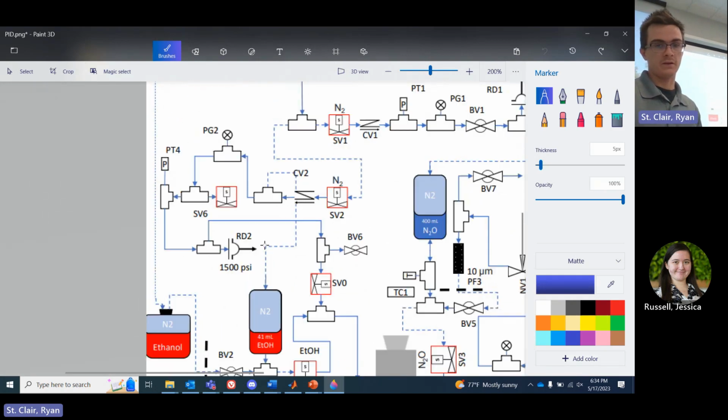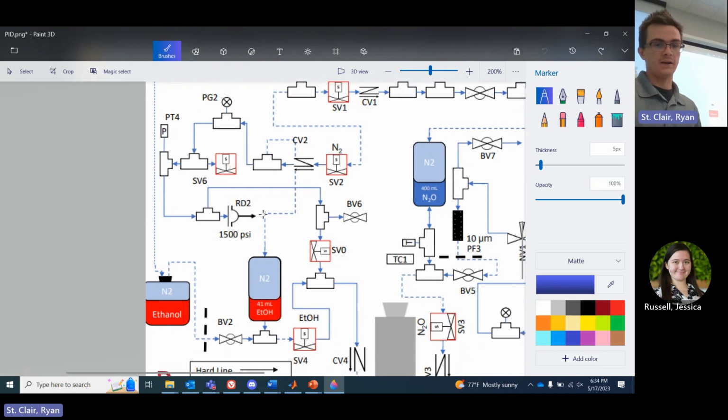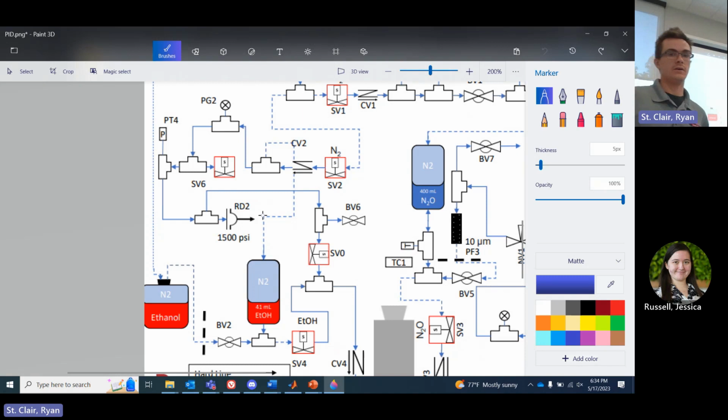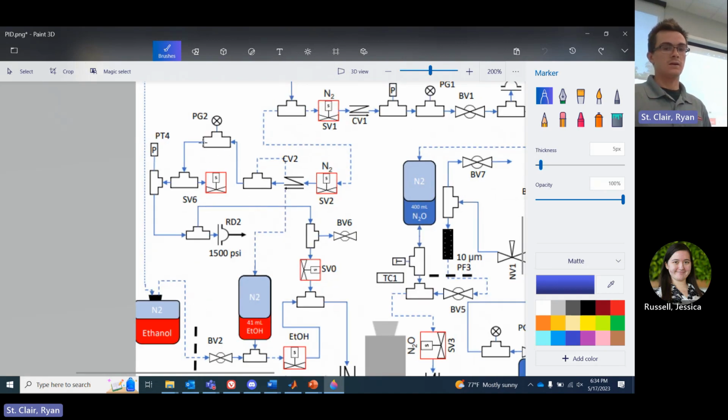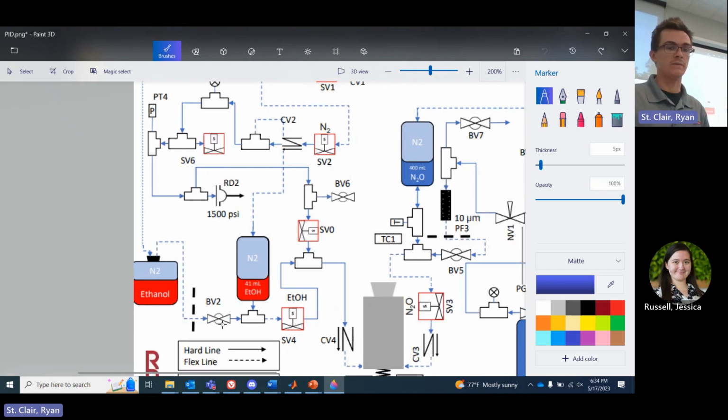And basically, I've just walked through all the components here. So it really is a step-by-step breakdown, looking at what different components do and why they're there. You can really start to understand that with a P&ID, and it also shows very well the relation of what lines are seeing the same pressure. If you're familiar with electrical engineering principles, if you have a conductor that is going to different parts of your circuit, along that same conductor you're seeing the same voltage. That's the mindset you have with this P&ID: when a line is never going across a valve or something, it's all the same conductor, all the same lines. So they all see the same pressure, except when you open a valve like this, then you can start to separate those pressures.